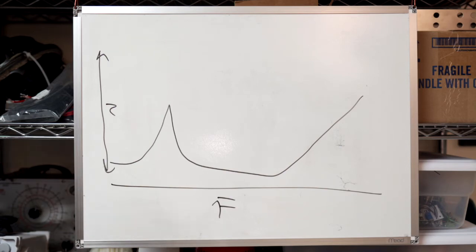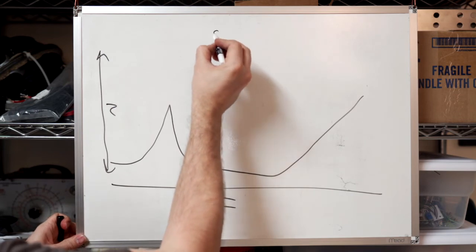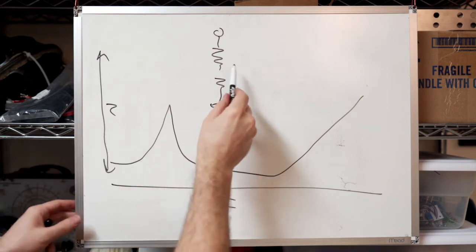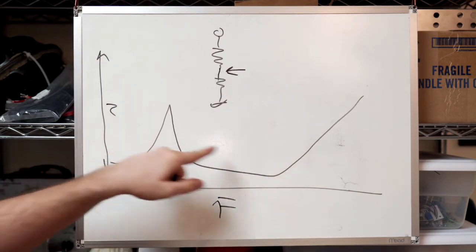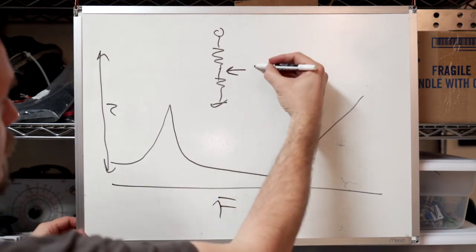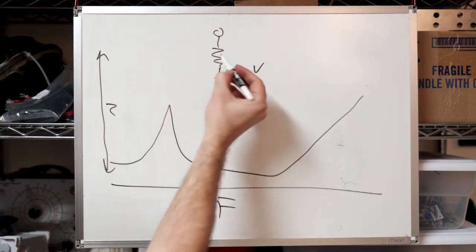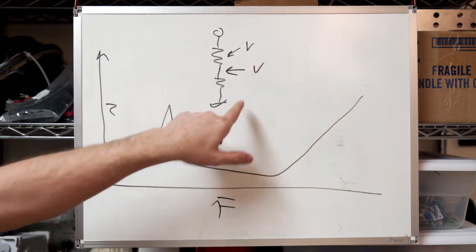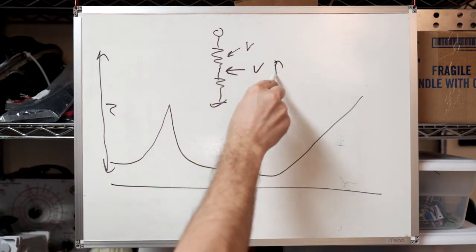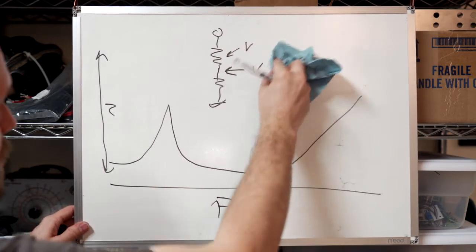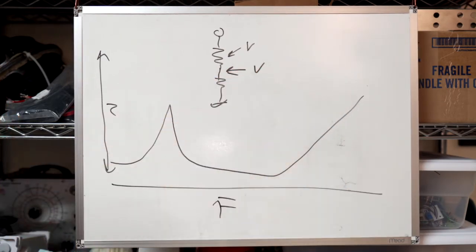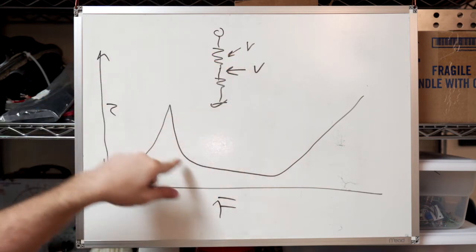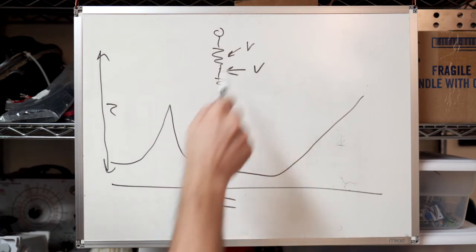So here's our voltage divider again. Here's our amp, here's the output impedance, here's the speaker, and we're looking at this voltage right here. Depending on what frequency we're amplifying, this voltage is going to vary a lot if this value is large. So now you're understanding maybe why they call low impedance sources voltage sources, because if you make this value very small, it doesn't really matter what the load does, this voltage changes very little.